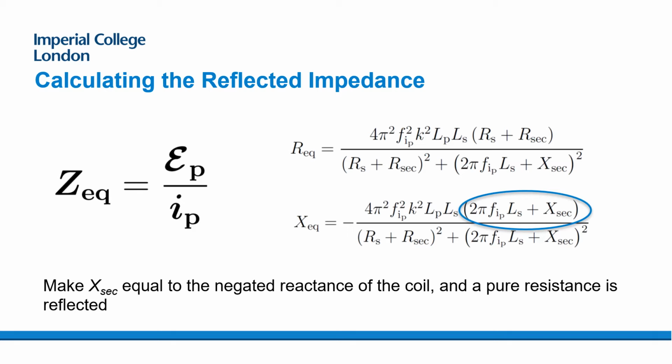What I would like to do here is to make the reflected impedance purely real, in other words, set the imaginary part to 0, because I don't want a transfer back and forth of reactive power across the link. As you know, any transference of reactive power must have a current flow associated with it. That current must flow through some copper, and consequently there will be losses. So I don't want reactive power sloshing back and forth across the link, and consequently I need to ideally resonate out the inductance of the secondary, as you've already seen in the previous talk, in order to set the reactive part of the reflected impedance to 0.